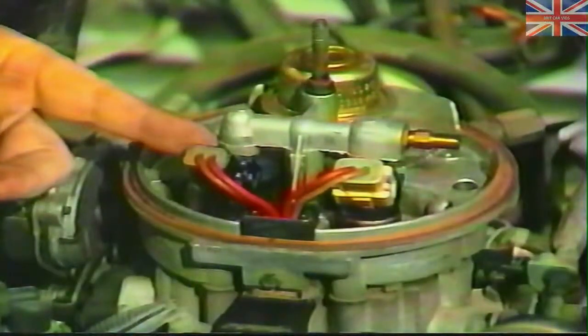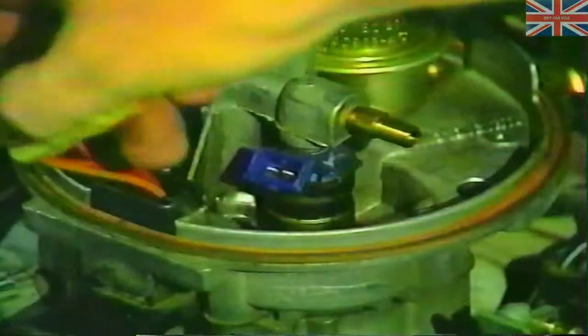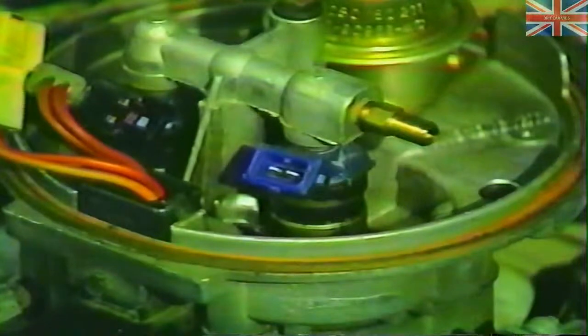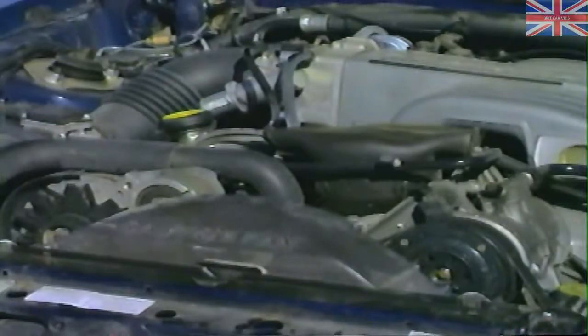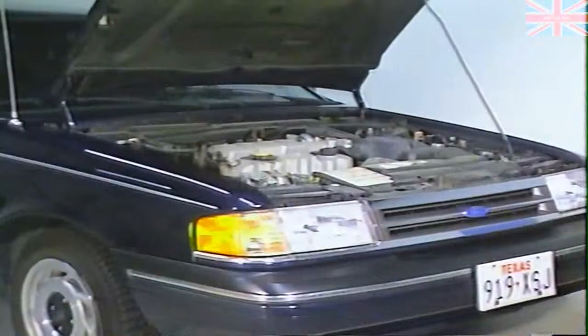The same EEC-3 system was again expanded in 1981 to include electronic fuel injection. The early fuel injection systems were actually throttle body assemblies utilizing one or two electronic fuel injectors. In 1984, EEC version number 4 was utilized on the 5-liter engines. EEC-4 was actually introduced in late 1983 on Escorts and Lynx vehicles equipped with the 1.6-liter electronic fuel-injected engines. The EEC-4 system offered expanded capabilities in diagnostics and the level of engine control over version 3. It continues to be Ford's main offering.